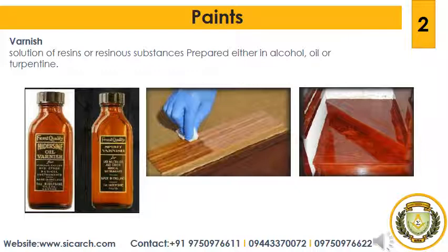So 1 N of glue will form about 1 liter of glue size. Alternatively, the boiled linseed oil can be applied in 2 coats. When the surface becomes dry, it should be once rubbed again with wallpaper. So the fourth one is coats of varnish.